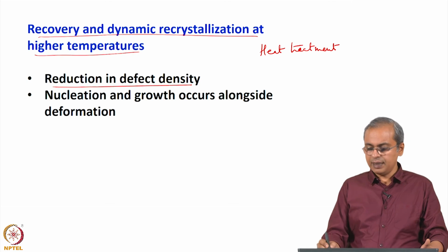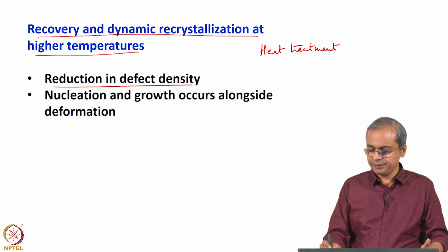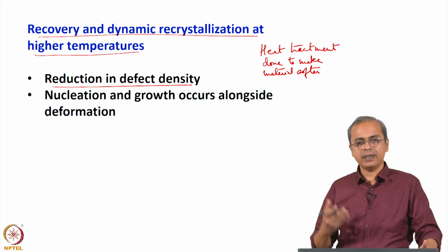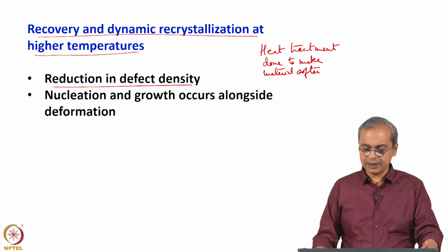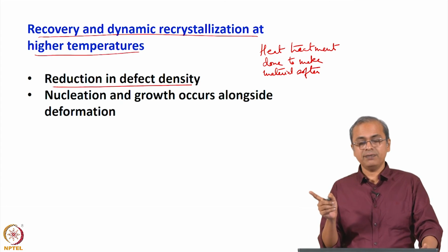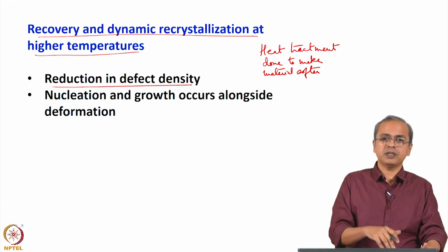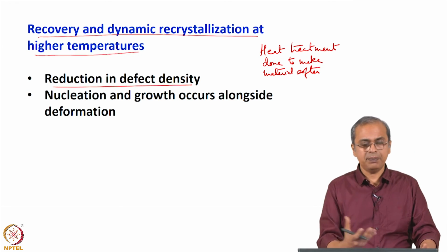Heat treatment is done specifically to make the material softer, so you can continue to do the deformation. So, from a manufacturing industry perspective, this is good. However, this is generally not good from an application perspective if the application happens to be a high temperature application.